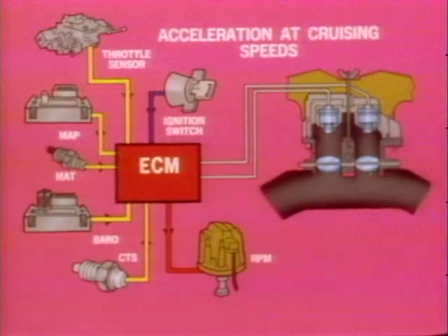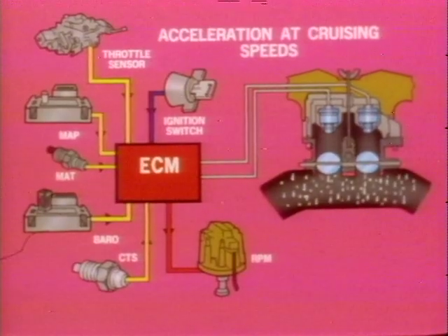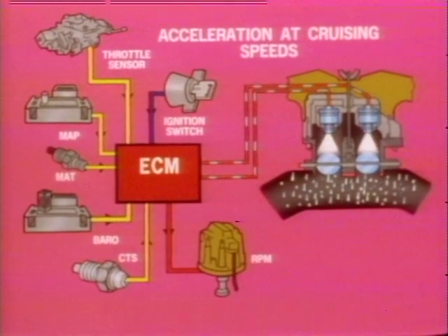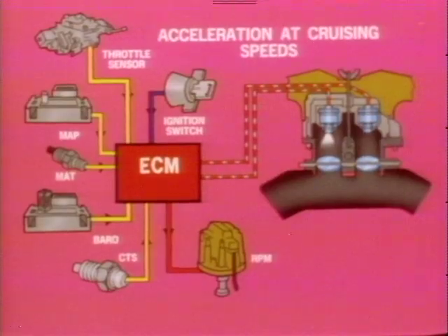When the throttle angle is quickly increased, fuel droplets condense in the intake manifold just as they did during the transition period from idle to part throttle. Additional fuel is supplied by simultaneously pulsing both injectors. The pulse width is dependent upon the rate and amount of throttle opening.